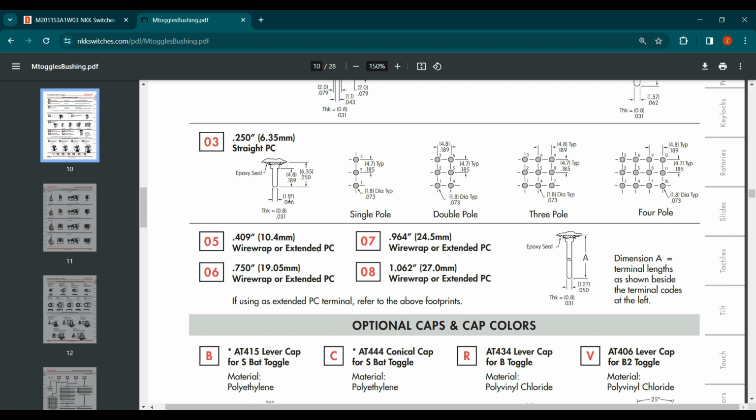These have a width of 1.17 mm and thickness of 0.8 mm. So if we have a circular pad, then our diagonal maximum pin dimension would be 1.42 mm.